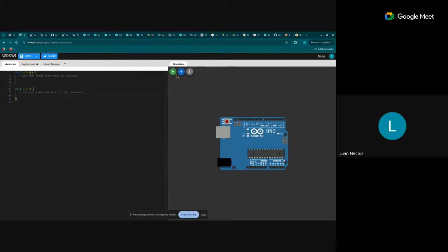So let's start with the basic hello world of embedded programming, which is blinking an LED. I am connecting this positive pin to pin 13 and the negative pin to the ground. These are digital pins, which means these are digital GPIO pins in their base functionality, which can be configured as either an input pin or an output pin. There are different configurations in that, and also each pin in GPIO can be set to high or low, which means on or off.